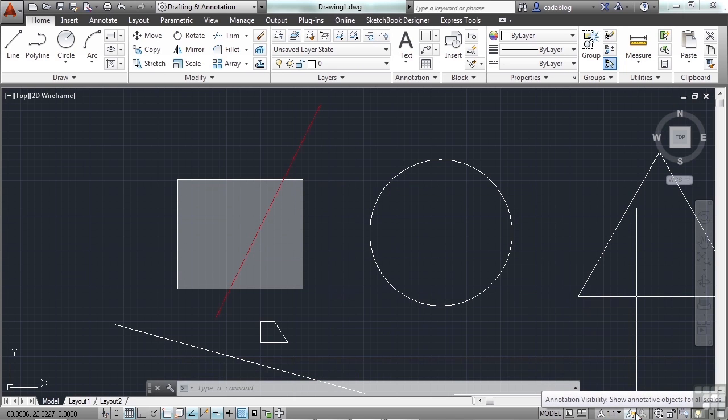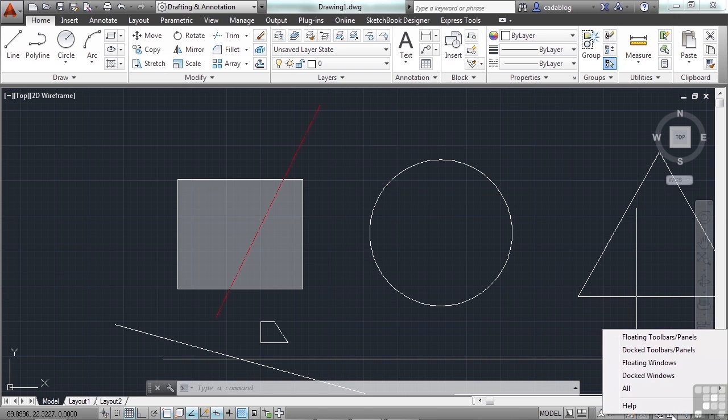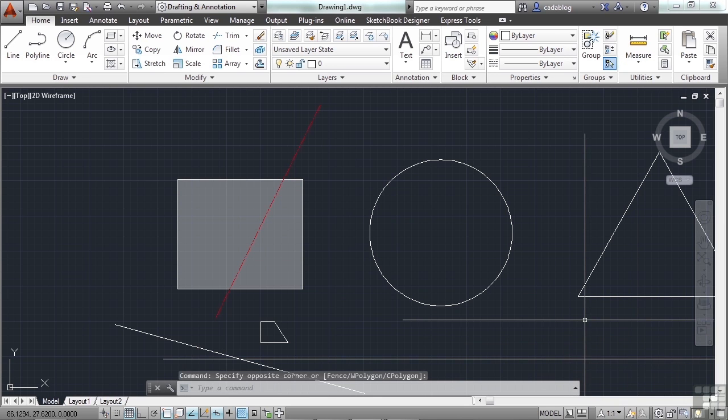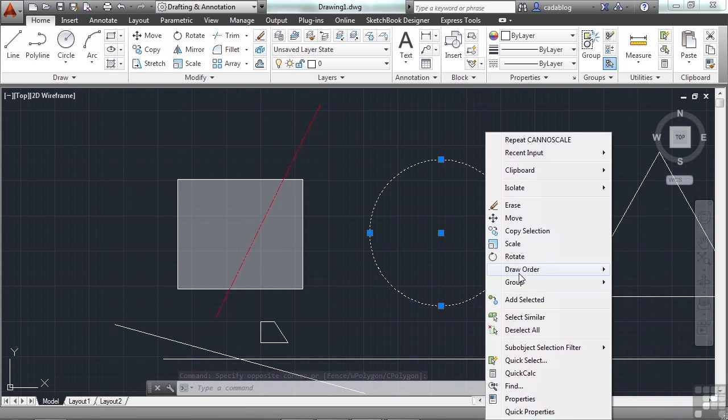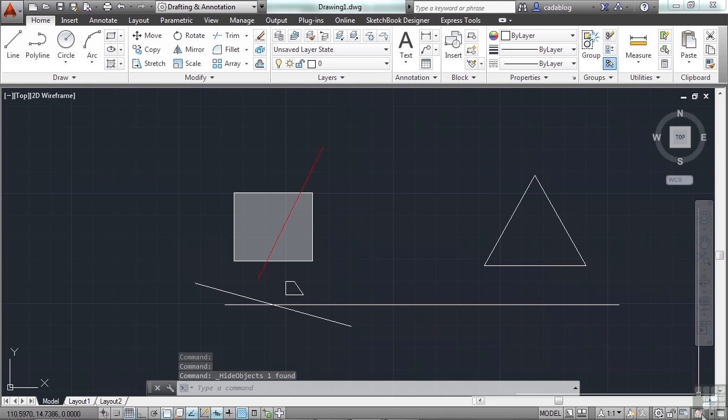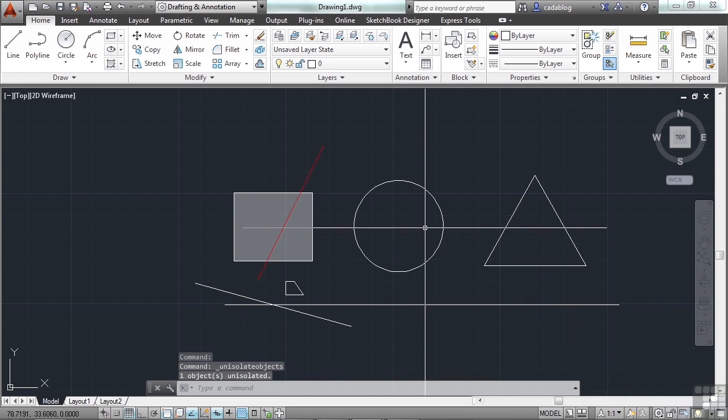These next buttons will control the visibility of that. And then your workspace switching, your toolbar locking positions. You can click this and you can lock them all into place, or you can, let's just let them go free. Let's have free range toolbars here. Let them go where they want or need to. And then you have hardware acceleration on or off and isolate objects. We'll show and talk about isolating objects later, but if I select and right click something for my default shortcut menu, I can isolate these objects one or two different ways. I can isolate just the object I've selected, or I can hide the object I've selected, or I can turn all this off. So let's hide that circle. It's still there. It's not gone. But you can see here now, my light bulb is now red. It's saying, hey guys, something's happened here. There's some stuff that's hidden from view. You may want to address that before you go too crazy in your drawing. So if you end that, and it comes back, and it's good again.